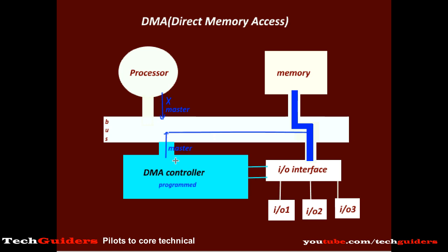But anyway, while DMA is using the bus to control the transfer between the memory and the peripheral, the processor will not be able to use the bus, but the processor may be able to perform some other useful computations. Also, by using one particular mode of DMA transfer, the bus can be intermittently used by the processor and the DMA controller, allowing the processor to continue with its work using the bus too. This can be used in case the peripheral is very slow.